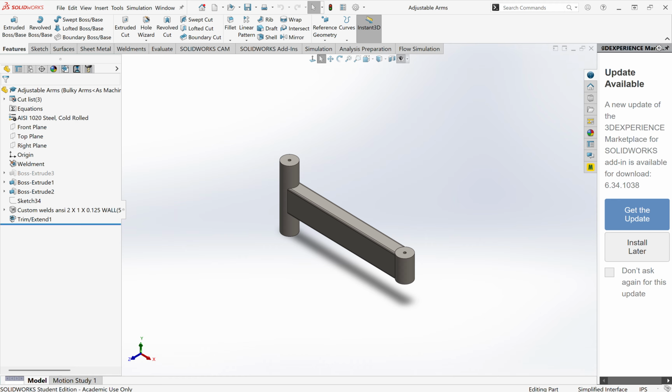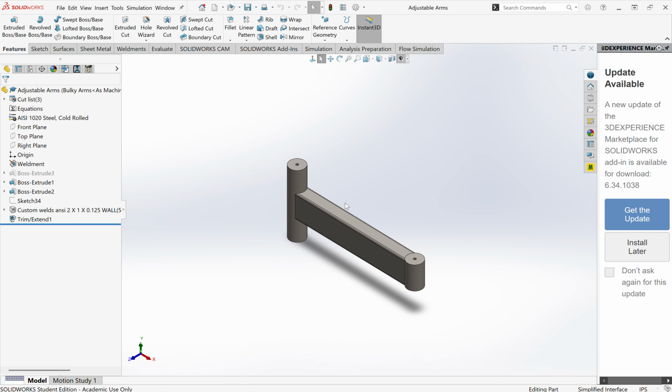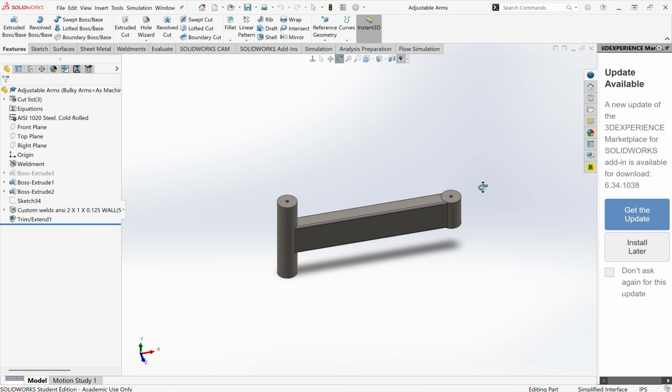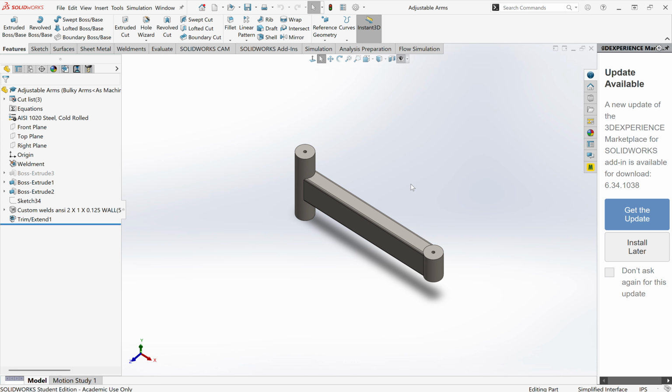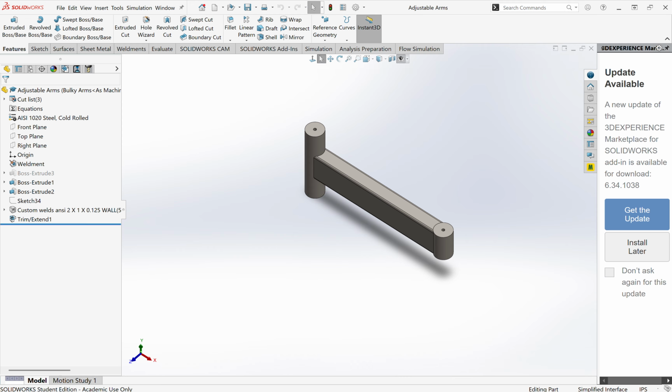Zoom controls in general. So zooming in and out, you want to use a mouse for SolidWorks. That's preferred. You can zoom in by moving your mouse wheel up and down, and then if you want to rotate it around, you can press on your mouse wheel in the middle and go back and forth. If you want to pan, which is just moving it from one part to another, you hold Control, and then you can move it with your middle mouse button.